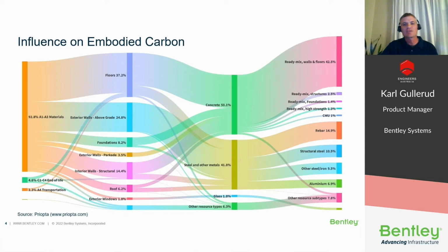As we just discussed, reducing floor depth reduces the overall building height and at the same time decreases the amount of exterior cladding required. So decreasing floor depth can also decrease embodied carbon in other ways besides the volume of floor material used. All of these points confirm that reducing concrete material and reducing floor depth can be efficient ways to reduce embodied carbon for building structures.